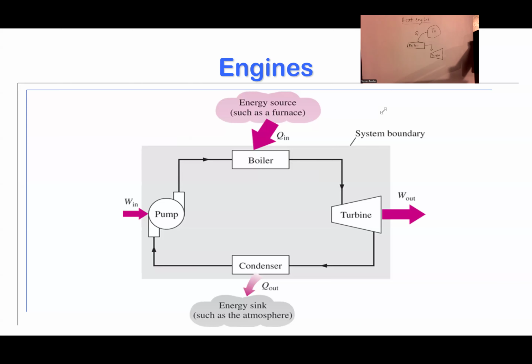That turbine then is going to extract, just like we talked about in chapter 5, work out of the system, out of the engine. Now, coming out of the turbine, I'm going to have a lower pressure, lower temperature steam, probably a very high quality mixture. We might simply get it down to saturated vapor, but we might go ahead and get it down to like 95% vapor, 5% liquid, a very high quality mixture.